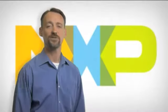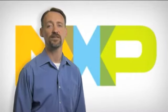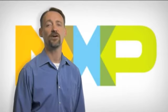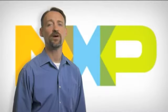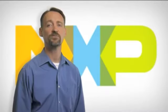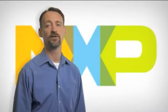Now, why would you want to choose a digital input? The primary reason to choose a digital interface is the robust immunity to RF interference. This graph shows two similar Class D amplifiers, one with an analog input, shown in red, and one with a digital input, the TFA9879, shown in blue. For each of these amplifiers, we brought a cell phone in transmit mode, close to the demo board.